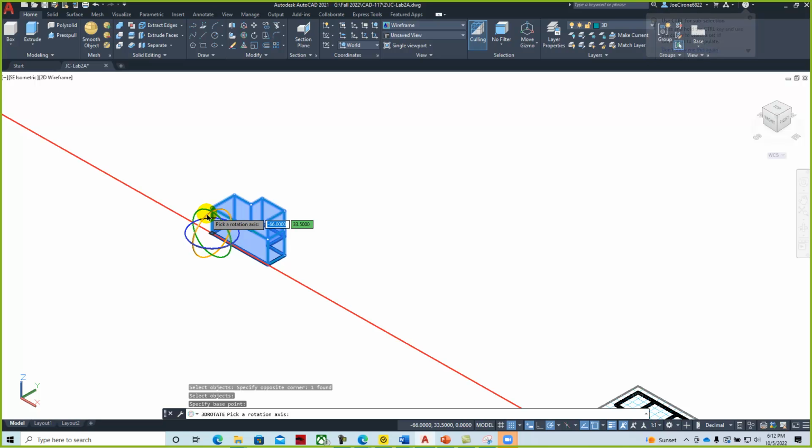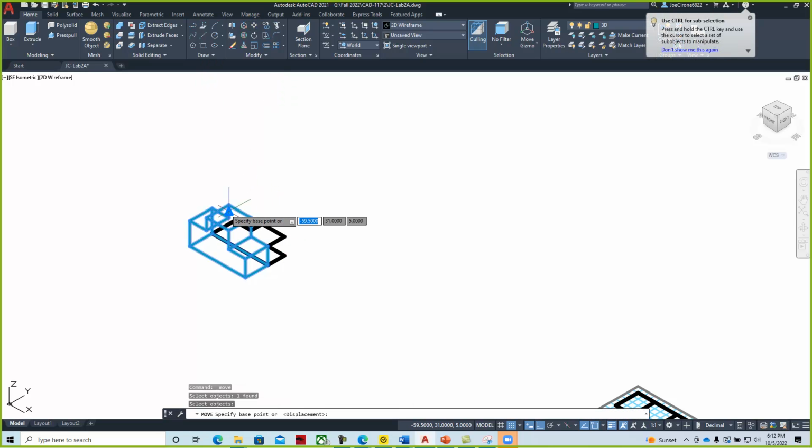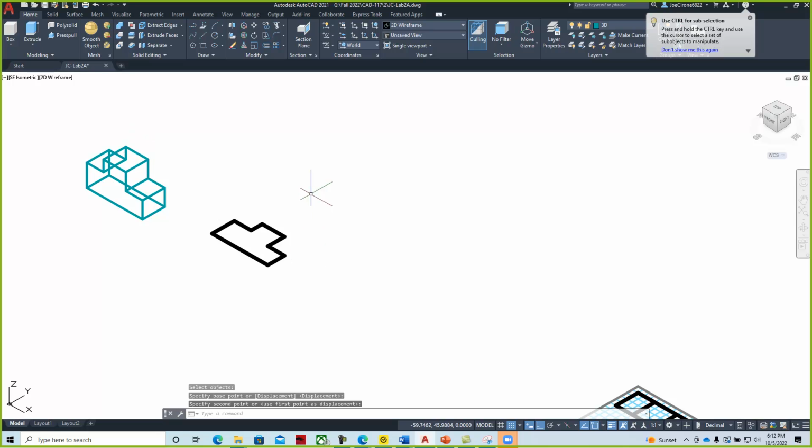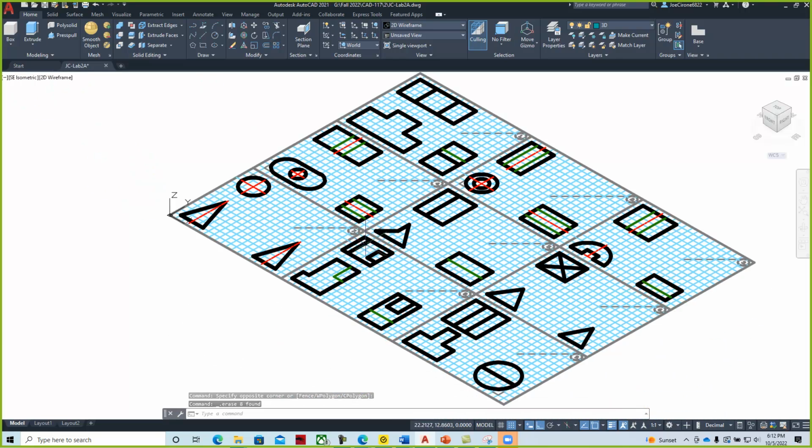Choose the axis of rotation. You're going to want to have polar on and possibly ortho. I'm going to put ortho on, and that way you don't have to worry about the model not being true or square. We have a ghost underneath it, so we'll move the part off the ghost image, erase the ghost, delete it, and then we'll just kind of continue through these exercises.